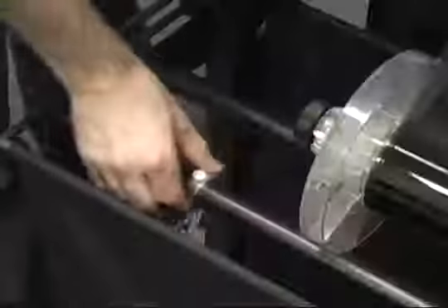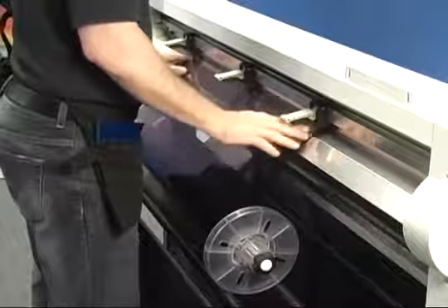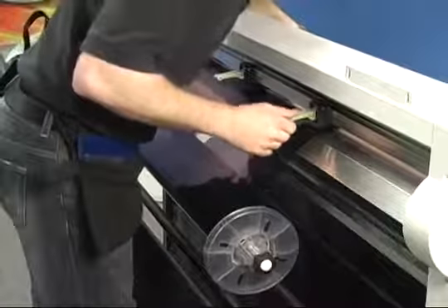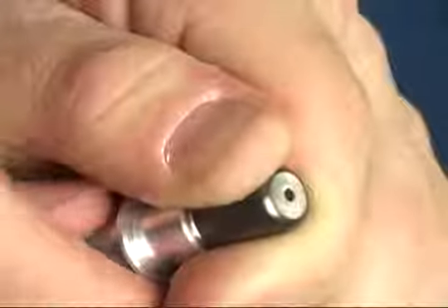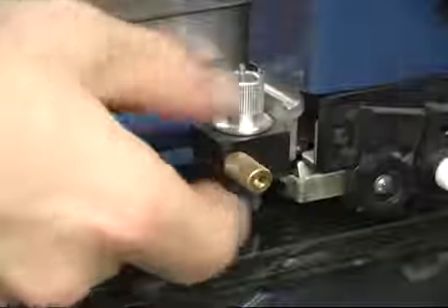The first thing you need to do is load the window film into the cutter. Next, you'll set up your GX-400. Lock down the pinch roll wheels. Then set the 25-degree blade in the blade holder. Set the blade extension to the thickness of the film.